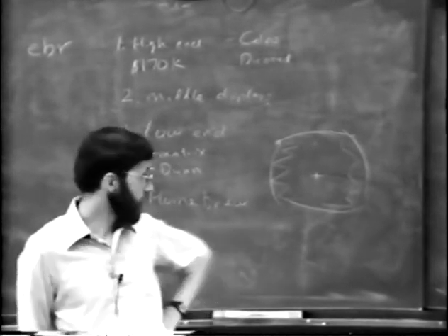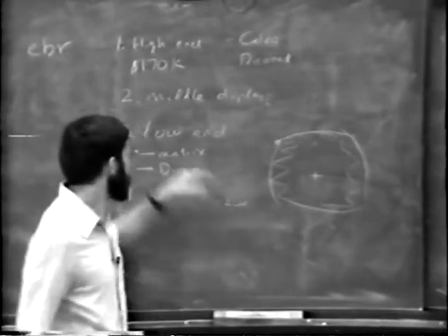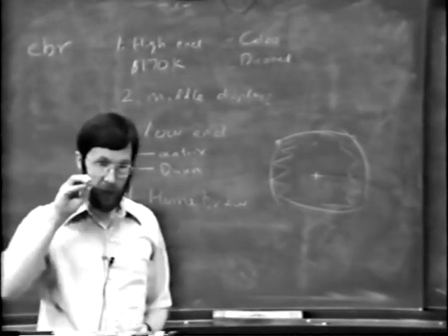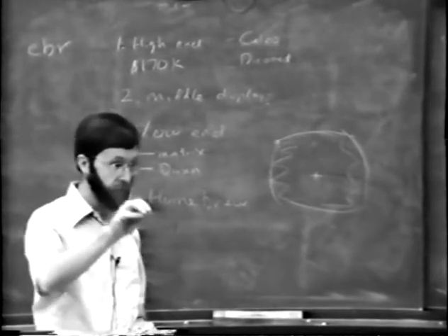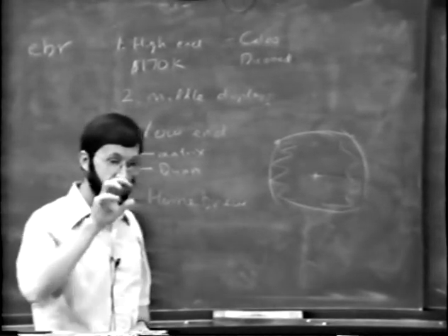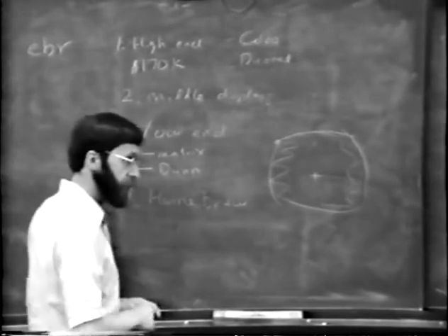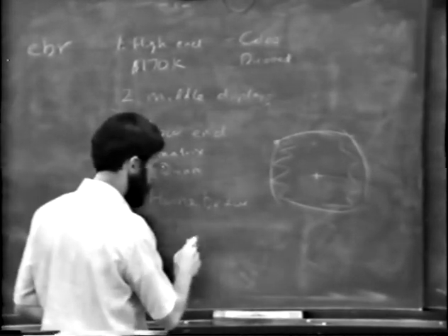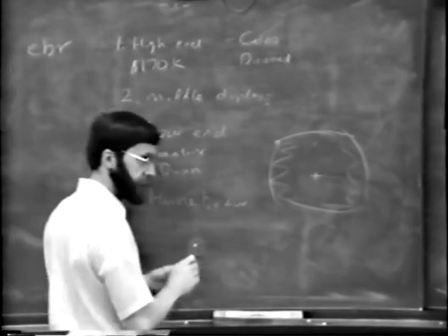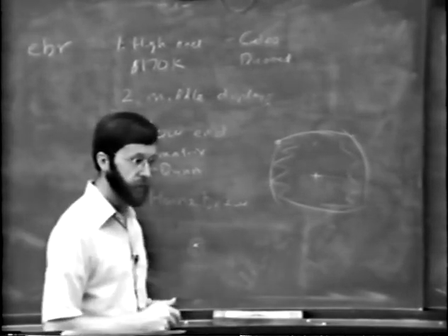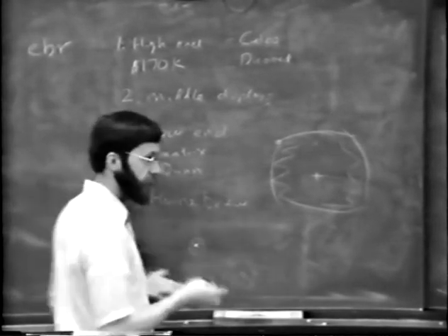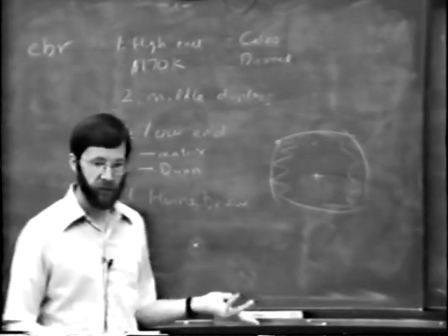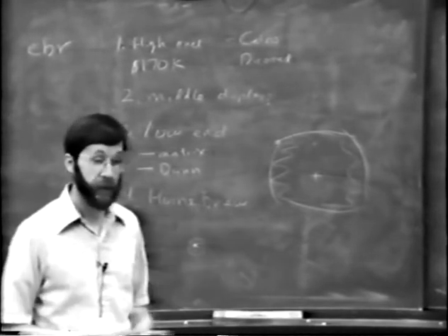But on the other hand, there are also problems with even these high-end units, where the electron beam hits the phosphor. Well, the electrons bounce off and then go back and hit it again. So if you've got the intensity jacked up, you see the beam, but you also see this circle around it. So it exposes this broader path that you don't want. In addition, you've got light bouncing around in the cavity. Right? So in general, you've got things happening that you don't want to have happen.